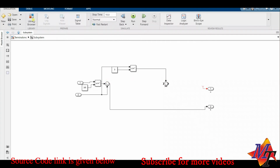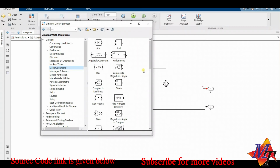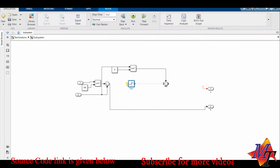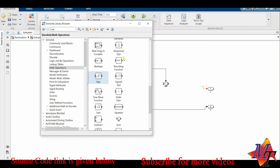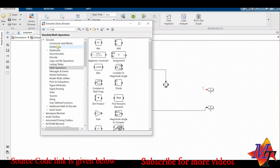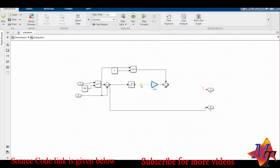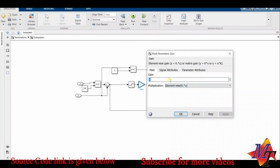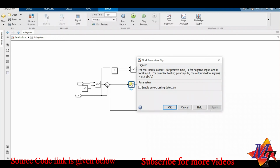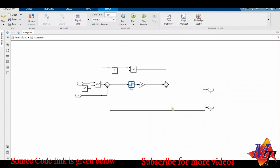So if we got this, now we will have minus 5.1 sin s. We'll again go to math operations. We'll take the sine function. Here we have got the s, so sine s into gain, that is minus 5.1. So we'll take gain and we have here 5.1 because it is already in minus sign. And while using the sign function, we have to make sure that the zero crossing detection is always disabled.